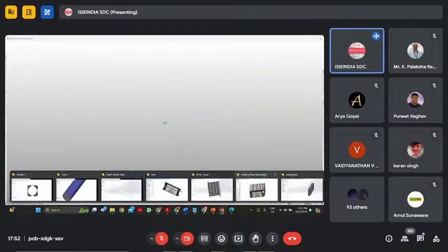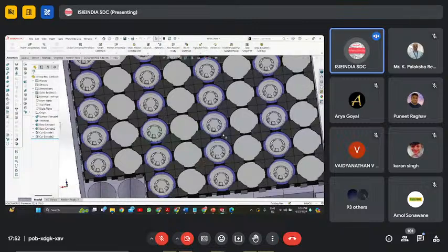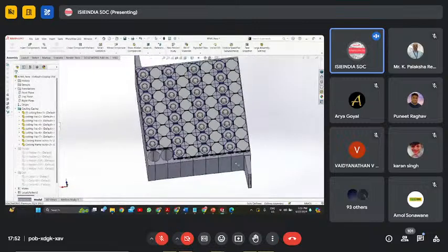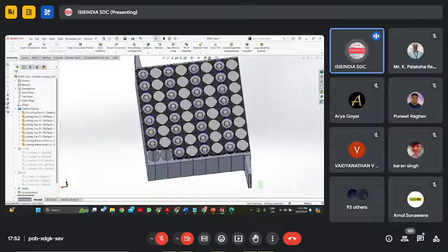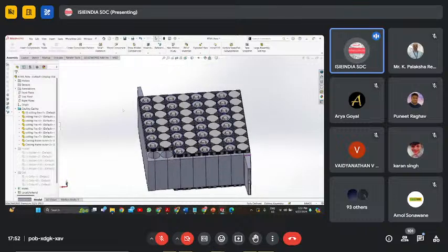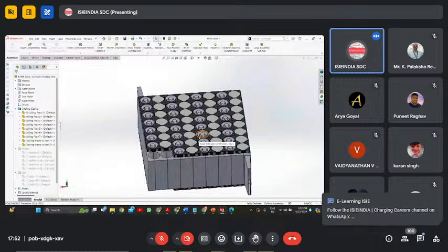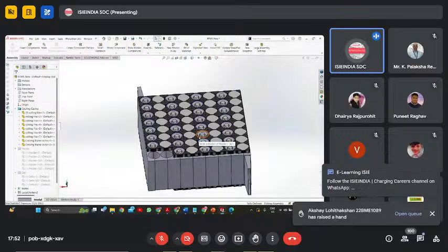With the help of a pump the fluid will be flowing. Suppose we input the fluid from here, it will flow like this, like this, and come out, and this goes on. So this is one kind of design you can do. Another option is a zigzag pattern. If you want air cooling, then don't make these channels, just make a compartment and use some other techniques. But you cannot say whether your design is correct unless you do the analysis.